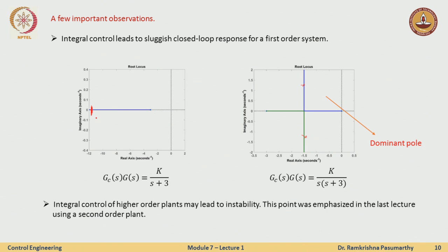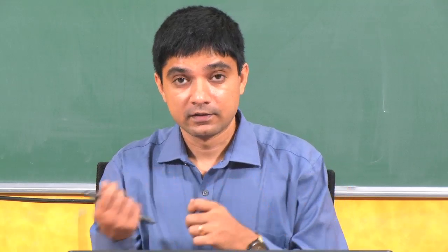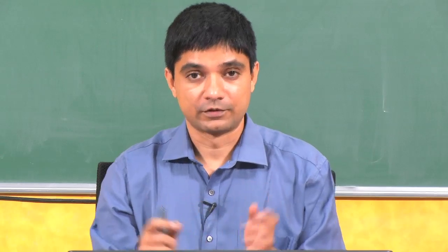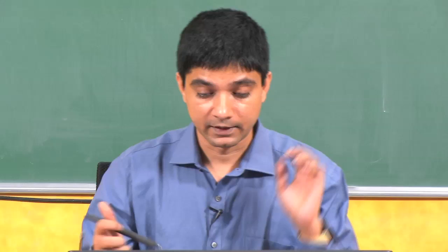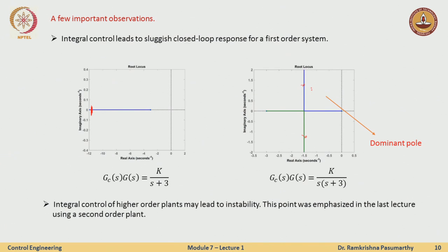So, this means that for that value of k where my pole without the integral action was say at -12 or -10 or somewhere in between, this response is faster than just having complex poles at -1.5 plus minus j something, right, which means the response has become sluggish, which means my poles, or what I would now define as the dominant poles, are now closer to the origin, and here the systems might be oscillatory, here they are not oscillatory. Okay.